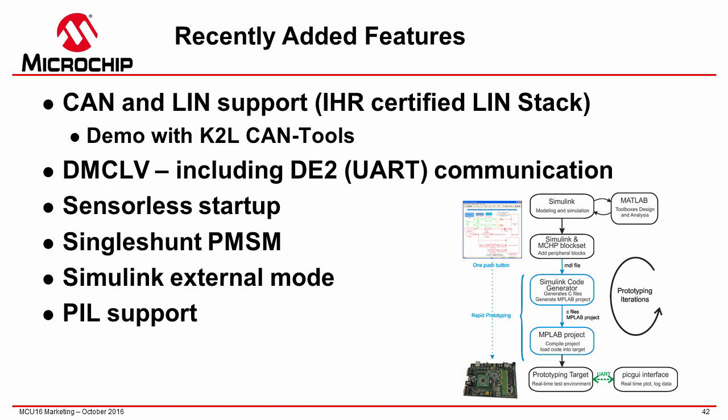We also support sensorless startup and single shunt for the PMSM motor. Additionally, we can support the Simulink external mode and processor in the loop, so you can verify if the simulation is exactly the same as the code generated for the microcontroller.